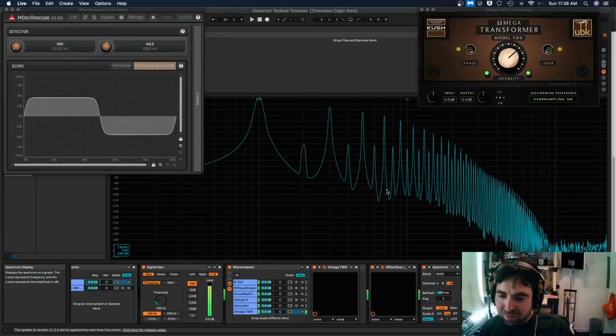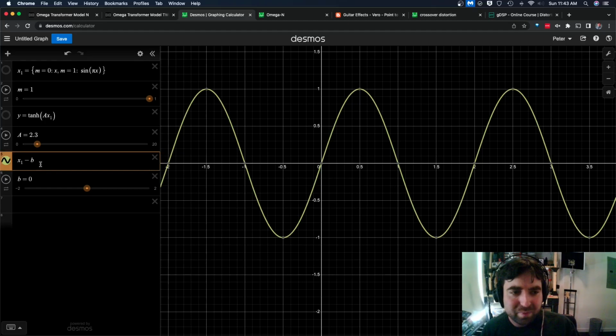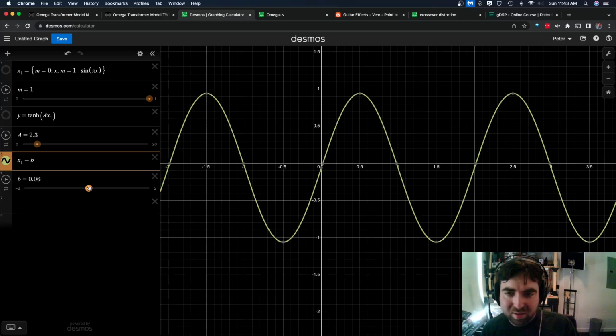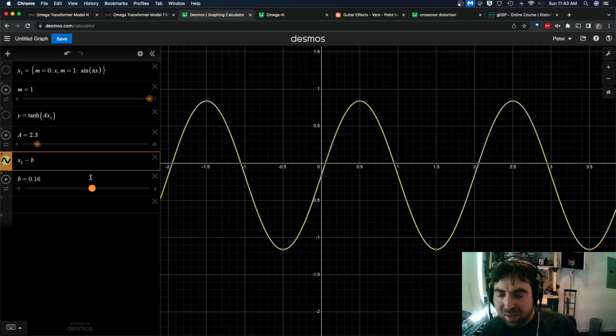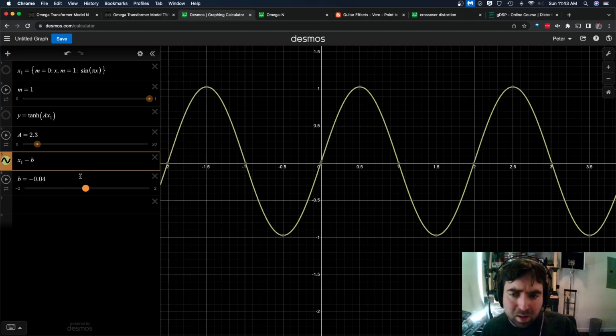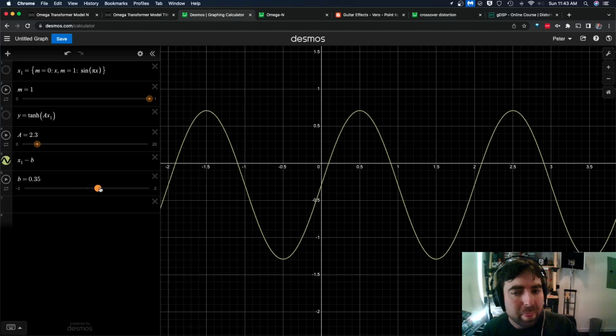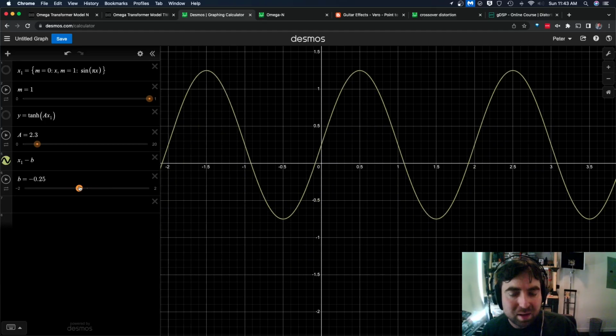So how do we get those? Here we have our sinusoid going from -1 to +1, as we'd expect. But in math, you can just add some offset to this, which is literally just adding or subtracting a constant number. In electronics, it's the same thing. You'd add a DC voltage to the AC signal, which is how those transistors and tubes are biased in the first place. So this is an important concept.